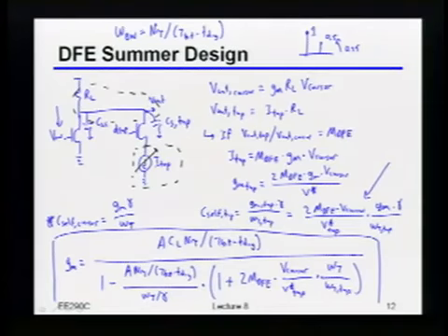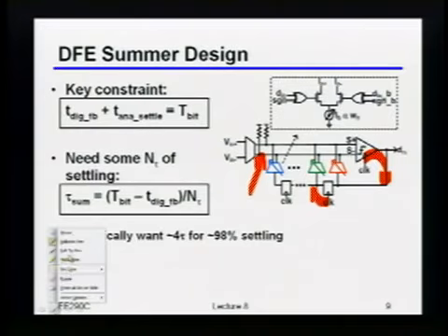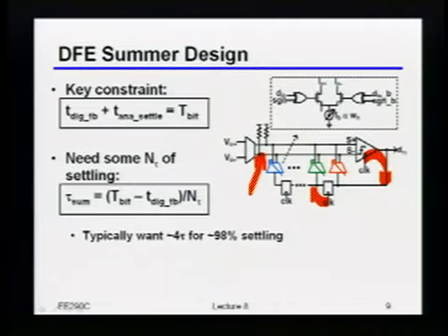Okay. Great question. I'll have to go back to this other picture to make that more clear. You're saying that each one of these switches could be flipped one way or the other. So I could have one data pattern where, let's say I had 20 taps, where 19 of them are flipped one way, and I'm just flipping one of them back and forth, right? Yeah. That will be very different than having 19 of them flipped the other way and flipping one back and forth. You're absolutely right. That will indeed modulate the impedance on that node,